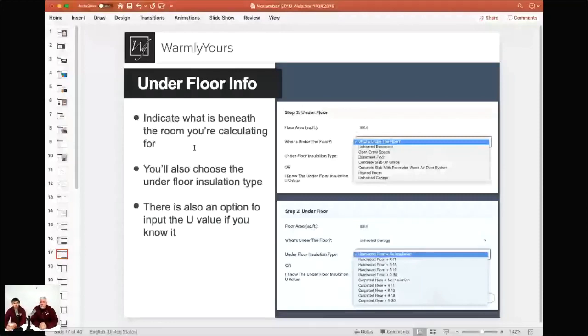But you don't want to just skip it, or always put best if it's not the best. Don't put the best, because then the system will think, oh, okay, there's just 10 BTU heat loss on this particular wall, while in reality, it's a huge monster there.